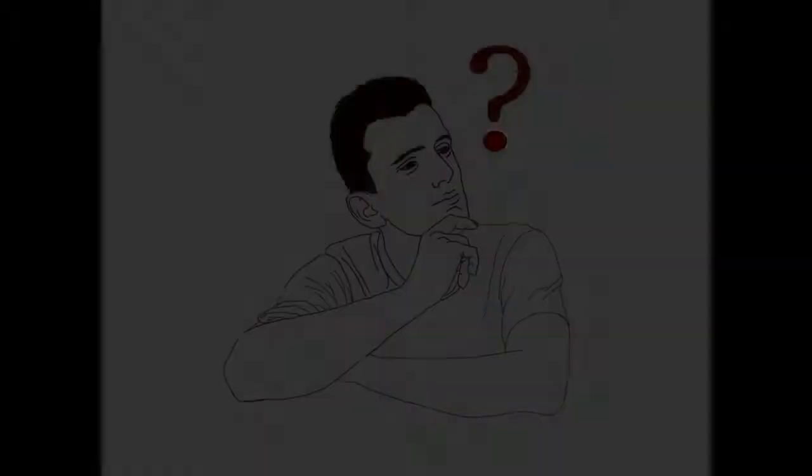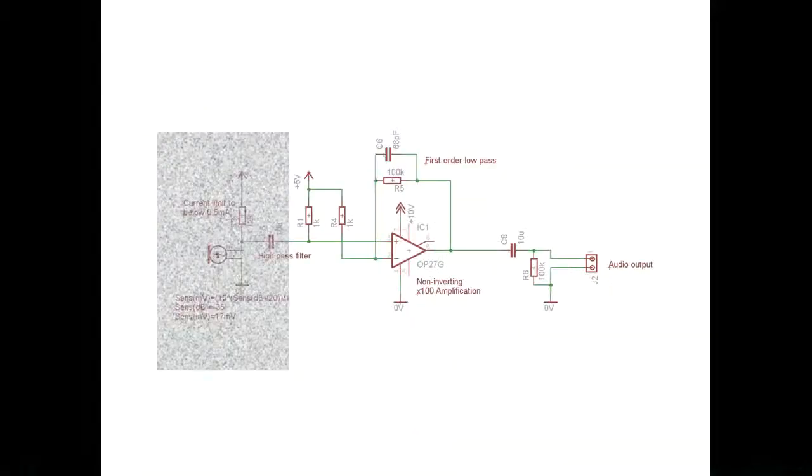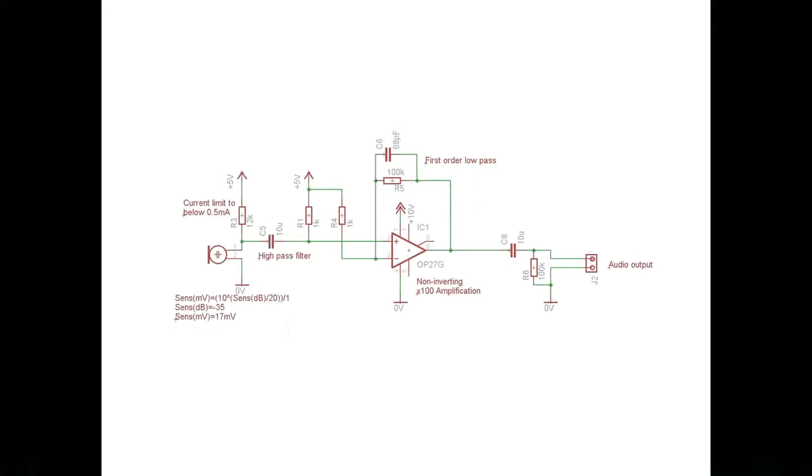But it's not perfect. So let's try to identify where the noise is still coming from. First, let's hear the ADC with nothing connected to it. Perfect silence. Good. No noise is coming from the ADC. Next, I will connect the amplifier without the microphone. This will show us how much noise is in the amplifier and supply bit. Amazingly, not a lot. And finally, time to add the microphone. So here is the main source. Well, it must be mechanical and some electromagnetic influence.